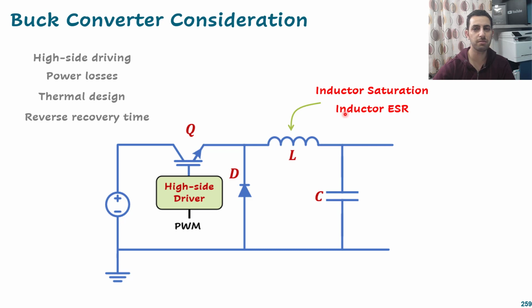Does it mean something for us? The same for the capacitor. We have something called capacitor ESR, equivalent series resistance, and capacitor ESL, equivalent series inductance. Okay, so that one has some inductance and some resistance. Is it important to look at these? Will that change the waveforms of the output voltage or output current? These are the questions that we want to reveal in this lecture.